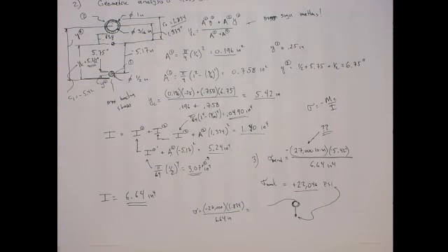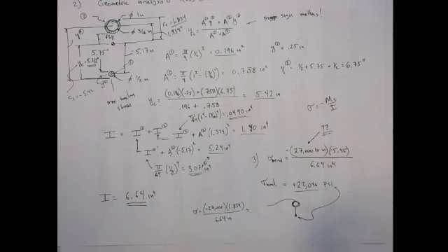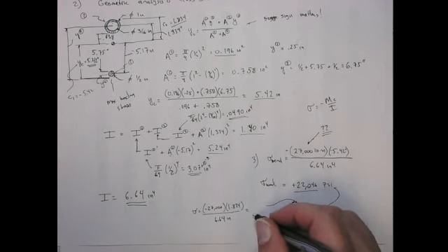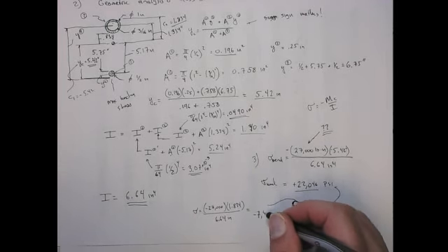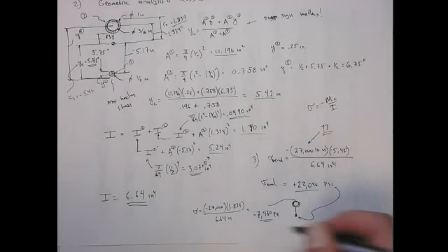And that turns out to be a minus 7,460 psi. Okay, so we got compression stress in here. It's much less than the extensional stress on the bottom.